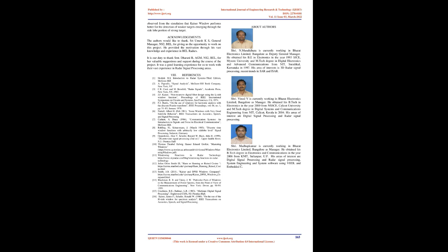7. Conclusion. In high-resolution radars, for improvement of range resolution, encoded waveforms like LFM, NLFM, phase codes, etc. are used. For detection of small targets which are close to bigger targets as per range resolution of radar, it is essential to address the energy leakage during matched filtering.